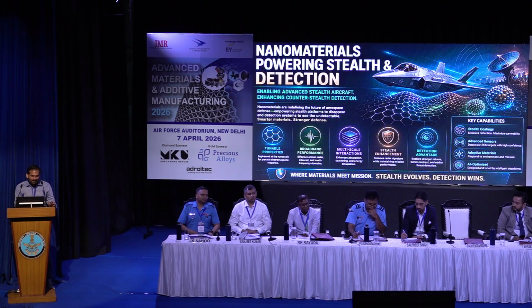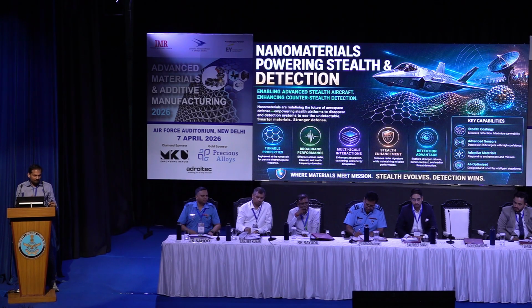So why are nanomaterials important? Because nanomaterials have a high surface area, tunable material properties, and broadband performance, meaning not narrow. We are creating a hybrid material which can perform over a very big frequency range, from megahertz to gigahertz to terahertz. If someone changes the radar signal to a different frequency range, the material can still control that signal.